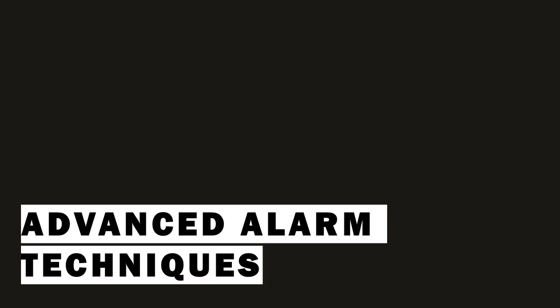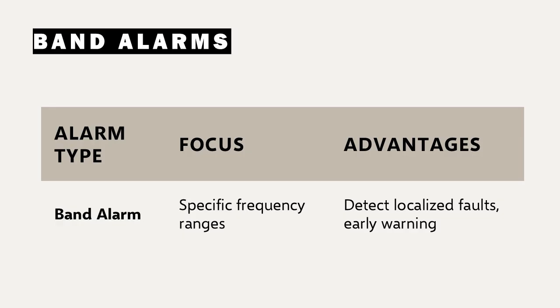Advanced alarm techniques, band alarms, envelope alarms. Band alarms focus on specific frequency ranges within the vibration spectrum, allowing analysts to monitor components such as bearings, gears, or shafts individually. By setting thresholds for these bands, it becomes possible to detect faults that do not significantly affect overall vibration levels but indicate localized issues.